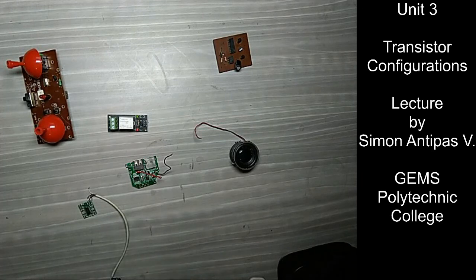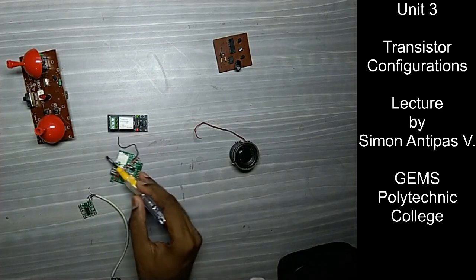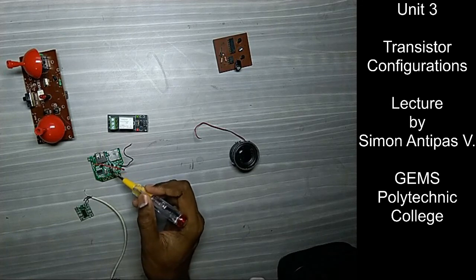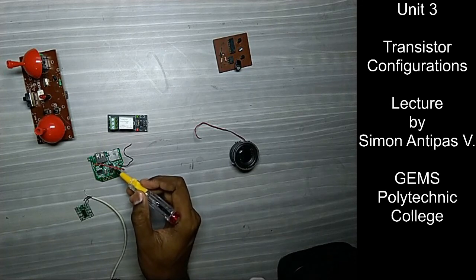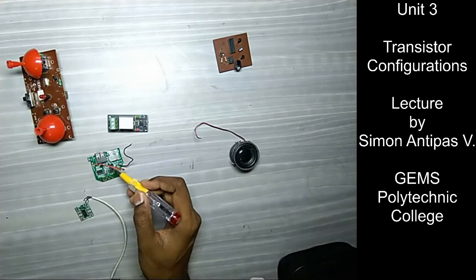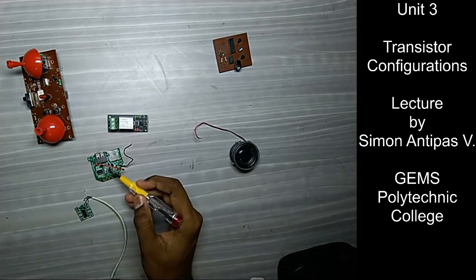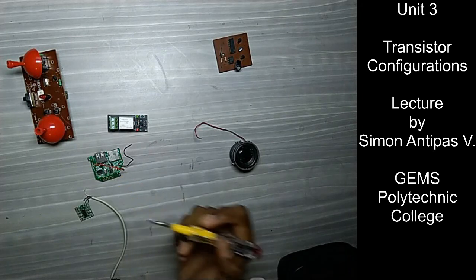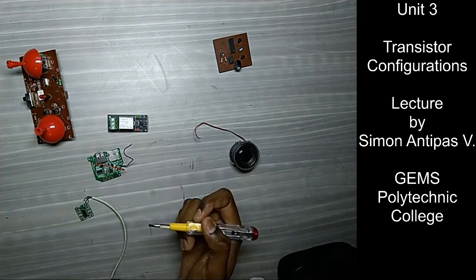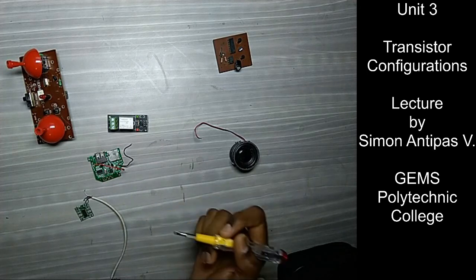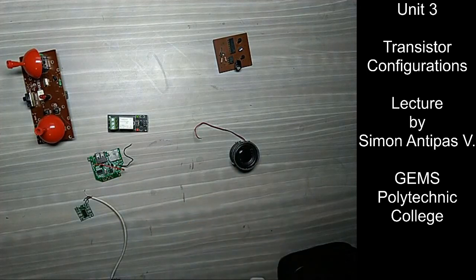So we talked about transistors. In this case, there is transistor-based amplification plus there is an IC-based amplification. So this transistor-based amplification can either be used in the pre-amplifier stage or in the final stage. In this case, you would see two transistors connected together to work together as an amplifier. So such amplifiers are very common, and you would see a larger version of them in bigger push-pull amplifiers, especially used in sound systems and in bigger auditorium-based amplifiers. Let's look at the theory behind it.